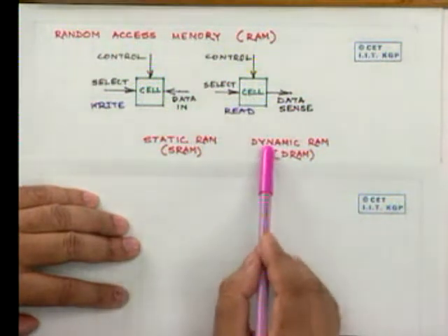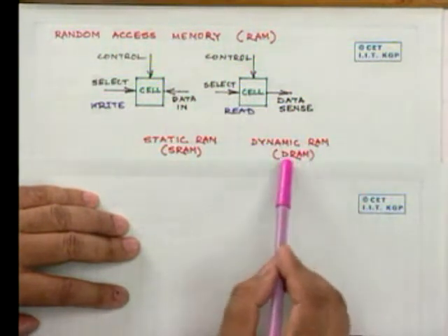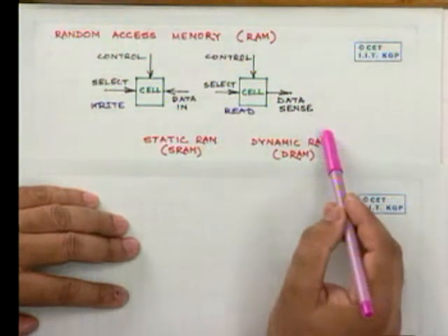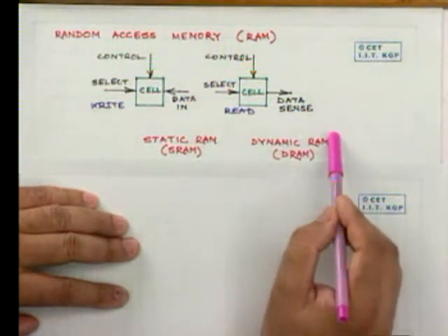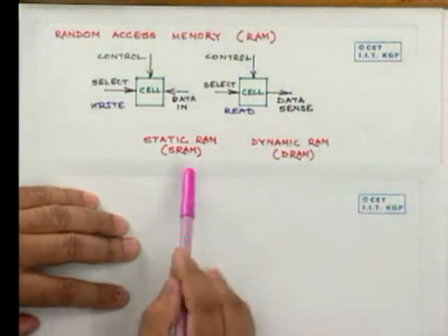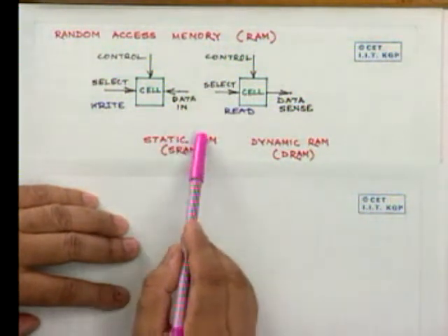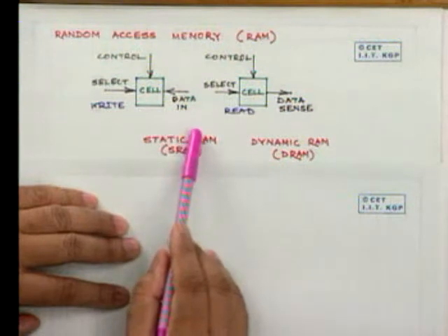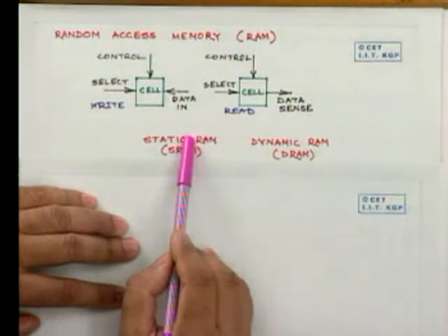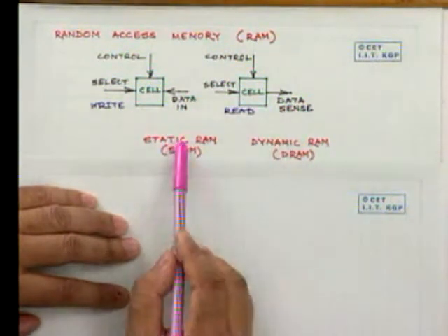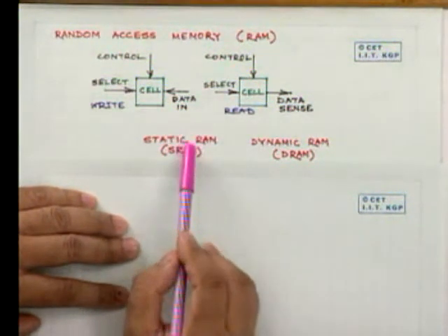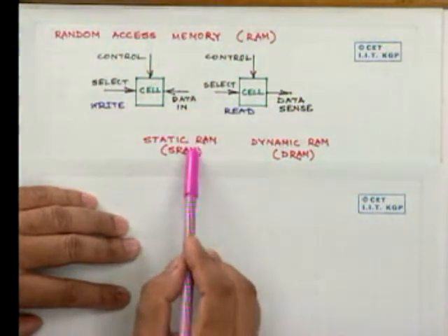In contrast, there is another kind of RAM, we call it a dynamic RAM or DRAM, where the 1 or 0 that we hold starts gradually wiping off. The reason I'm telling this is that in the case of a static RAM, it's an interconnection of several active devices, making it a flip-flop, so to say. And that flip-flop contains either a 5-volt or a 0-volt, depending upon whether it is 1 or 0. When I say 5-volt, it's near 5-volt. When I say 0-volt, it is near 0-volt.